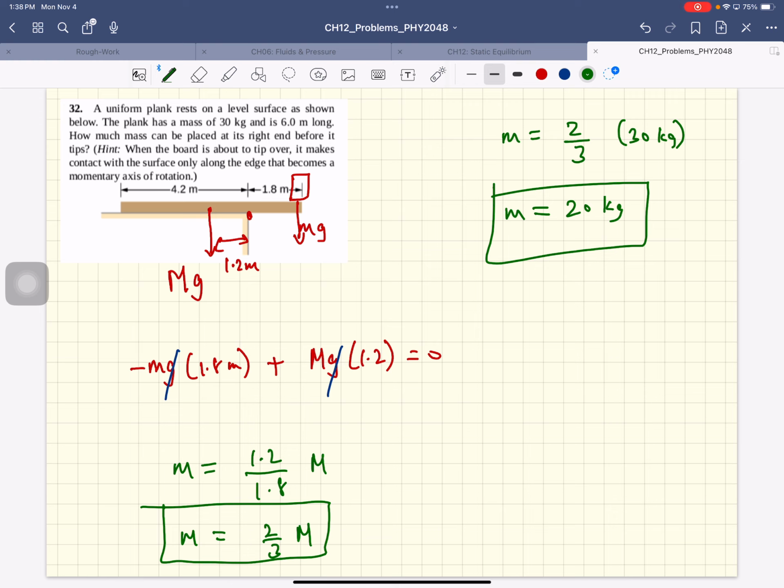Again, if this was some kind of application in a warehouse, if you want to support larger masses, what would you have to do? You'd have to move the plank to the left. Either that or make the plank heavier. And if this was a scaffolding and you want to support large weights, then you would have to nail this thing down.